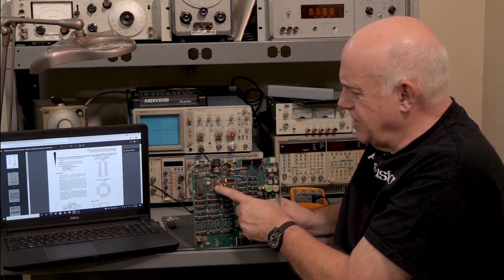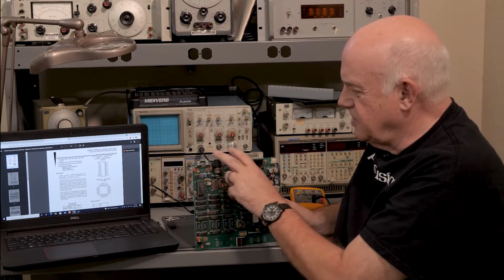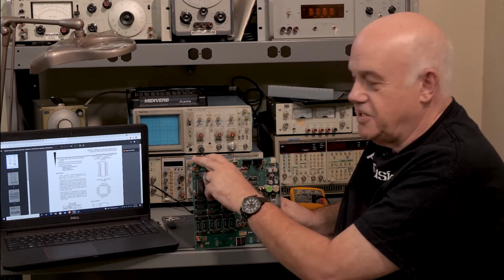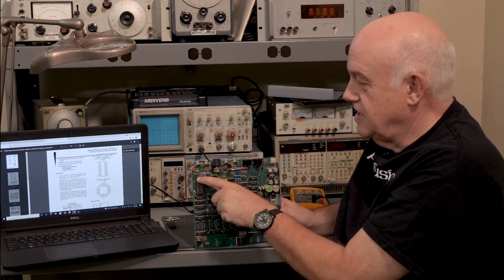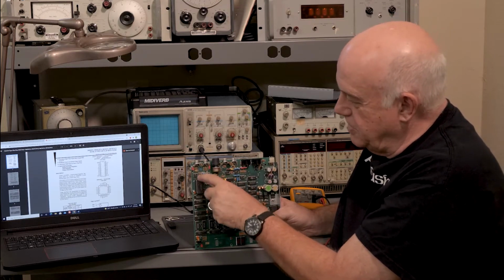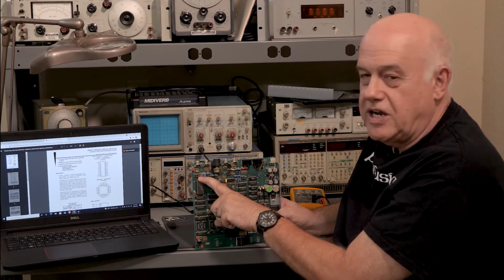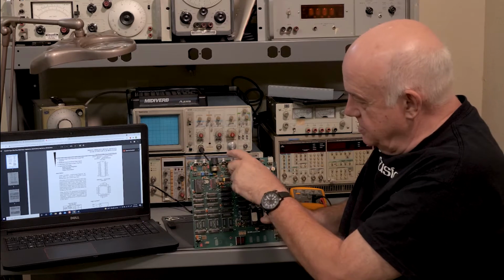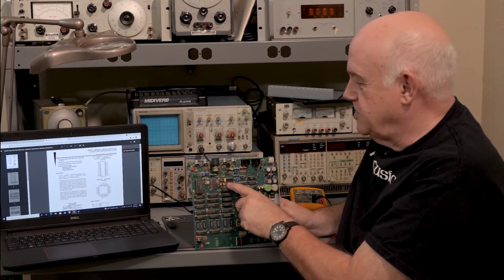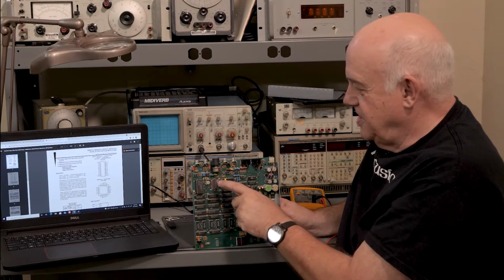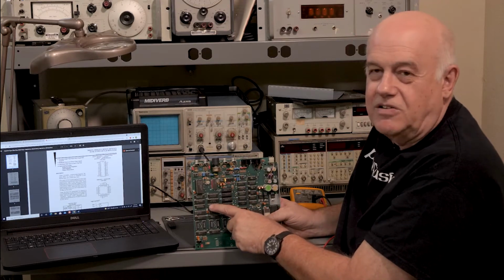Well, there's only one DAC, stereo in, stereo out. What's up with that? Well, it turns out that it's not true stereo in. They mix it. So the first analog thing I did was I debugged that real quick and said, there's only one analog input. They're cheating. But it has true stereo outs. We'll talk about that. How does it get true stereo outs? And the answer is, with only one DAC, they do a little software trick.